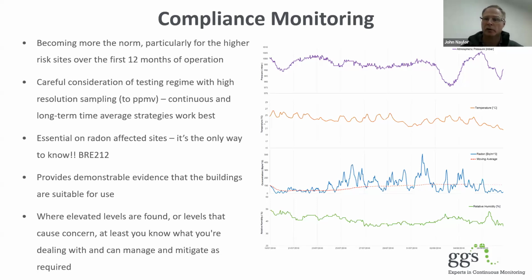Make sure, just like we did with the investigation, that the technologies, the methodologies, and the equipment being used are suitable for the task. Has it got the right resolution? Has your sampling strategy got enough visits in place to actually get enough good quality, strong confidence data to say with confidence that we are happy that those pollutant linkages have been managed and mitigated?